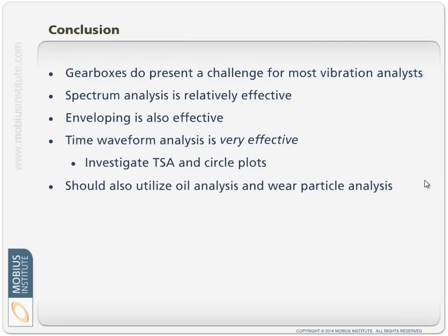Spectra are useful. Enveloping and the various techniques are useful. Time waveform analysis is very important. Have a look at time synchronous averaging, have a look at circle plots if your software has it. Think about the criticality of the gearbox and how important it is that you get all this right. Think about the failure modes and the PF interval to make sure you're taking your measurements frequently enough. And also think very carefully about oil analysis to make sure it's being lubricated correctly without contamination, and about particle analysis so that you can detect those particulate contaminants but also detect any wear that's going on.